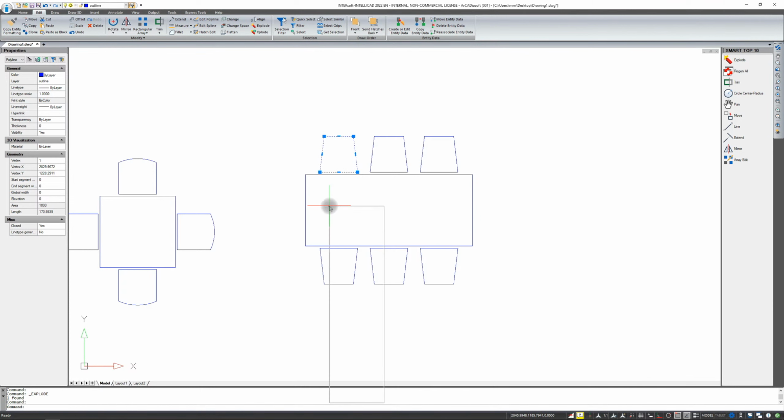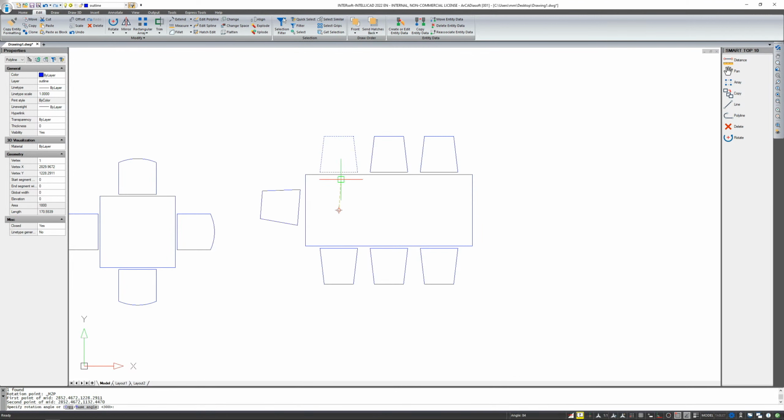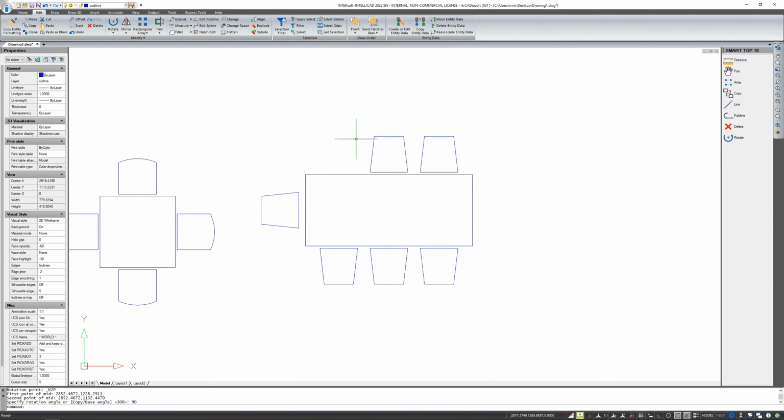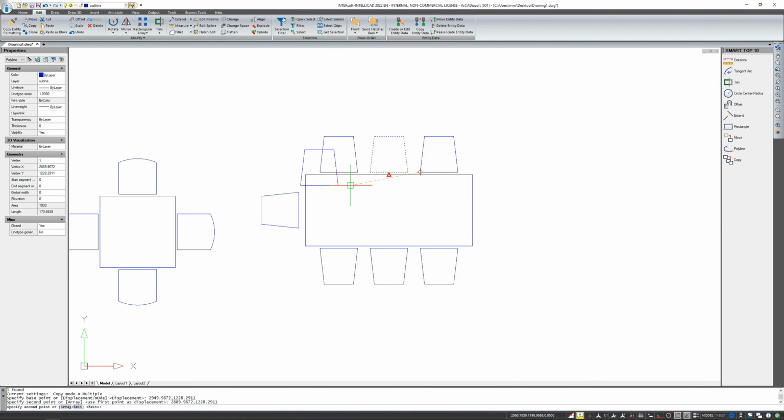After you've done that, I choose the rotate option because at the same time, I will show you the option Shift and the right mouse button, which is pulling out the list of snap points. I choose the middle one between the points because I want to be positioned exactly in the middle of my inserted chairs. And now the points, but I forgot about the copy option. So this chair moved, but that's okay because I can always use the copy option in a very simple way. And as you can see, the same distance is measured. Now I'll use the mirror again.